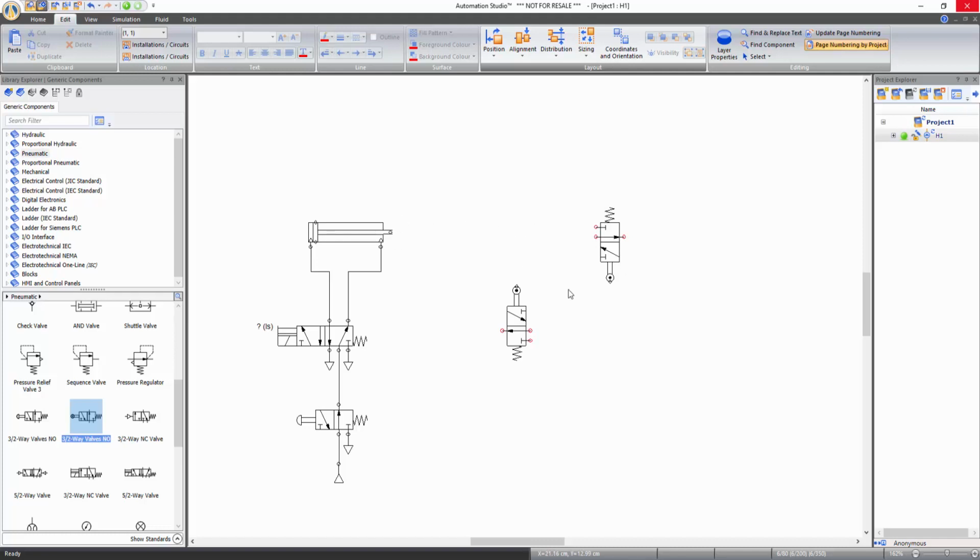To do so, move the directional valve to match position of diamond at the end of the cylinder's rod with the diamond on the mechanical sensor of the directional valve. Now position the mechanical sensor of the second directional valve at the end of the cylinder's stroke.